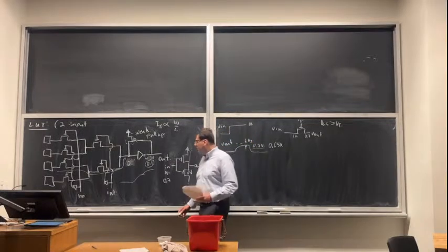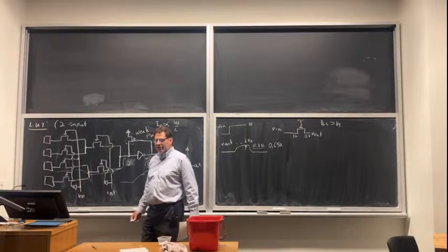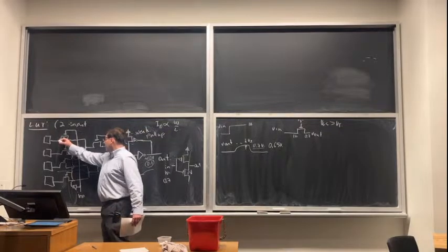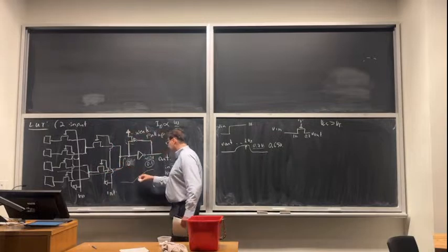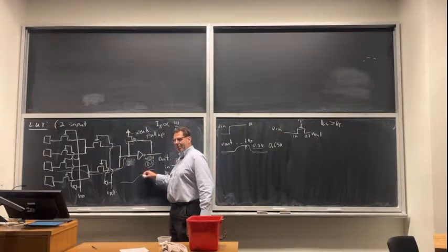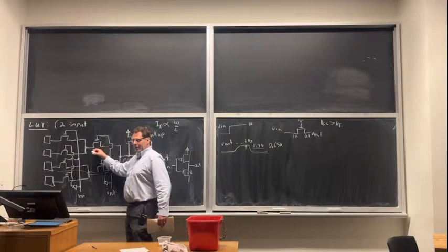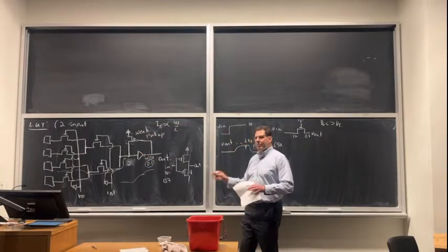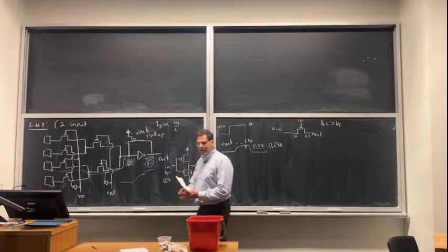Does a weak transistor mean that its current driving capability is vastly less, compared to that last stage and most transistors? Yeah, it has to be quite a bit less. So basically, I have to essentially double the resistance of these to account for the fact that there are 2 of them. They also are barely on as they approach this 0.7 volts, so they're weaker still. So you would want this to be significantly more than twice as weak as one of these, more like probably 5 times weaker than one of them. You'd actually do a bunch of SPICE simulations to see what seems good, but you want it to be pretty weak. Does that make sense?